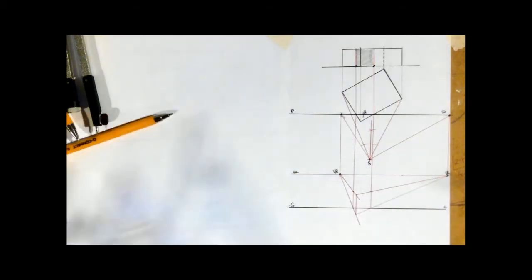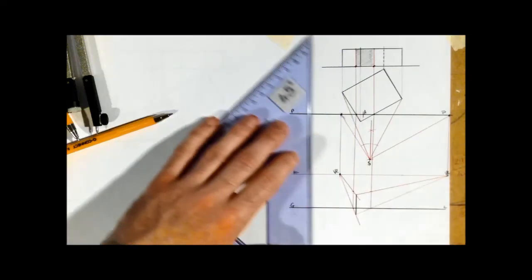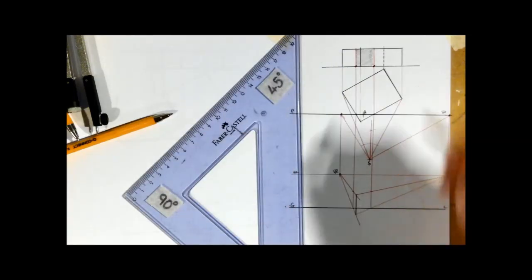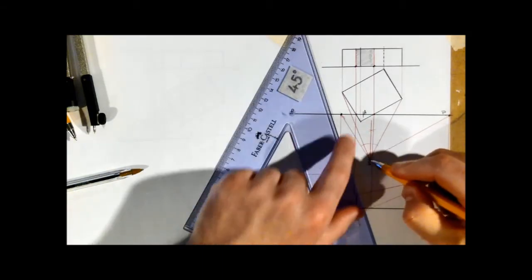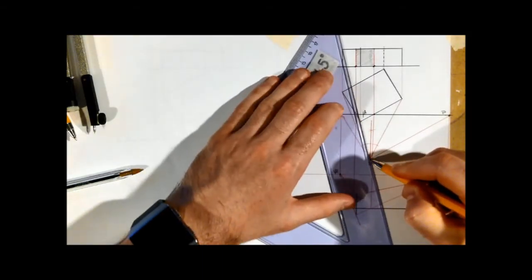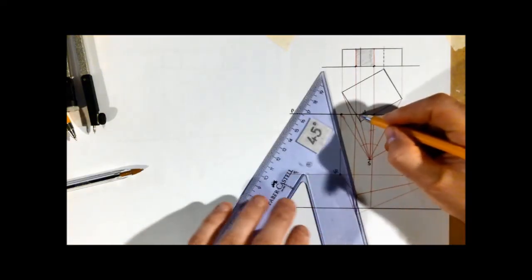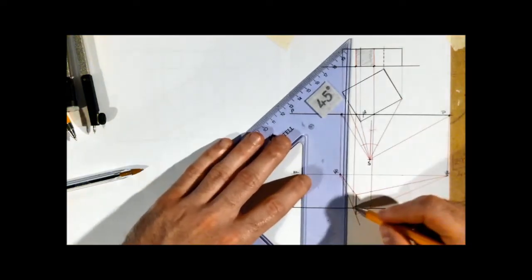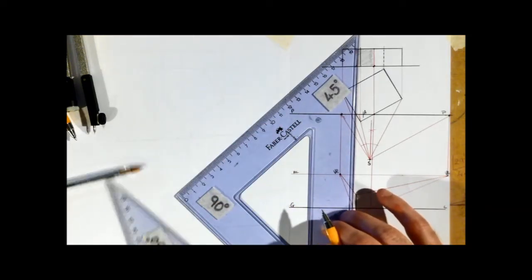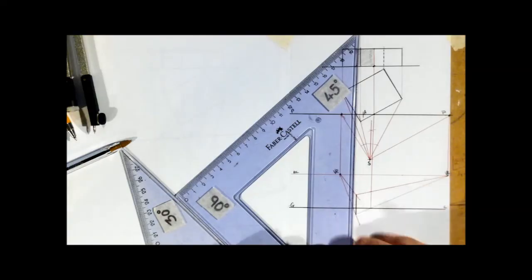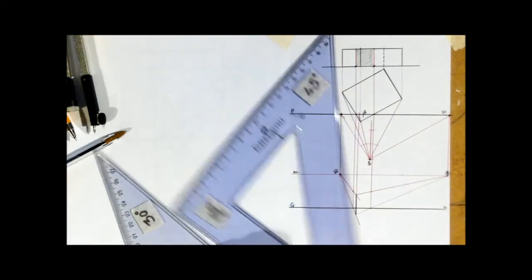Okay, so technically what we've actually found there is finally now the front corner, which is here. Okay, and to be able to prove that, it would be the spectator's view of it. So the spectator would look at this point, project it up where it hits the picture plane, and drop it down. And depending on my accuracy, and hopefully I'm accurate enough now, we'll see how accurate I was, it should line up with this edge here. And close enough it does.